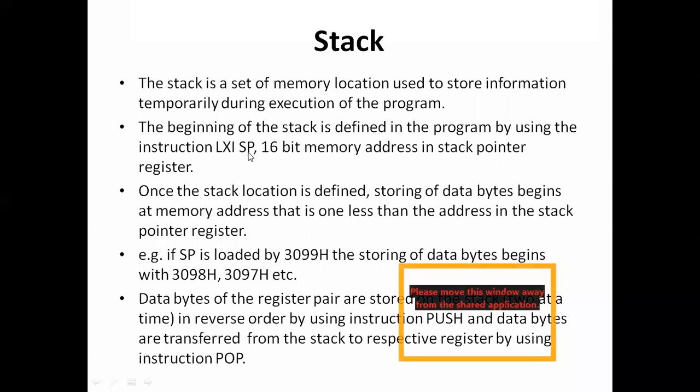By doing this, what will happen? The 16-bit memory address will be stored in the stack pointer. And this stack pointer, which contains a 16-bit address, will represent the memory address from where that memory can be used to store the data temporarily in the form of a stack.